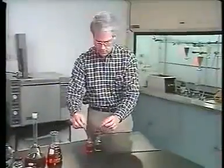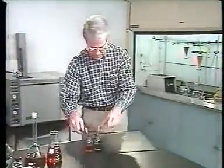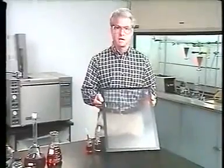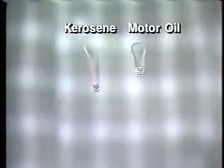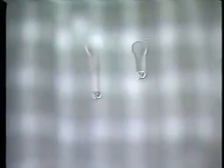All fluids have viscosity. Let's look at 2 liquids and compare them. I'll place a drop of each liquid on this glass, and when I tilt the glass, you'll see which has the greater viscosity. As you can see, the slower liquid is the motor oil. This means that it has a greater resistance or opposition to movement. It has a greater viscosity. Though this demonstration was simple, it's basically the same way in which viscosity is measured in the lab, by timing the flow of a liquid.